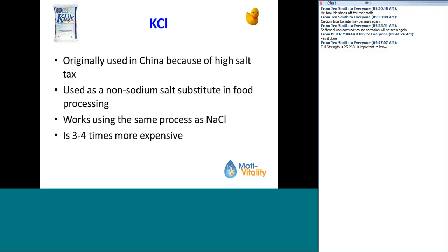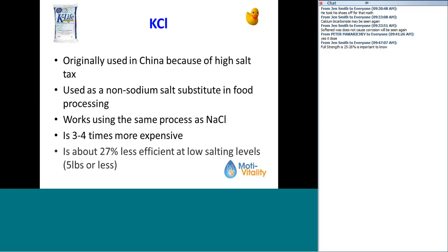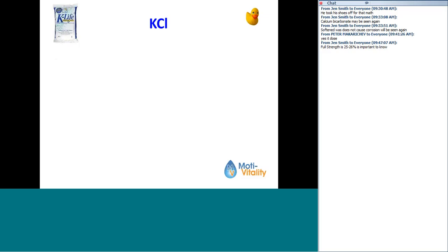It is 3 to 4 times more expensive than regular sodium chloride, and it's about 27% less efficient at low salting levels. That means 5 pounds or less. Once you get up over 5 pounds, then it equals out. The salting efficiencies come to be about the same. But if you have it set at low salt dosages, then it's going to be less efficient at the lower levels. It is good for people on low or no sodium diets.